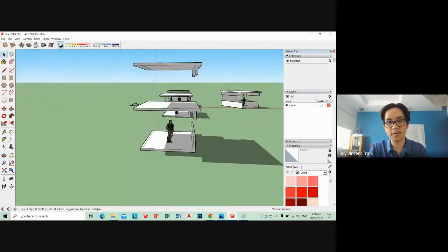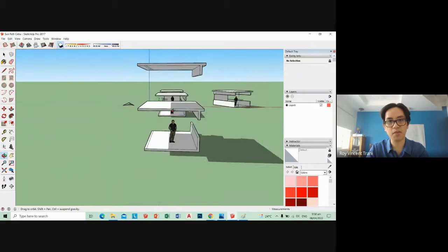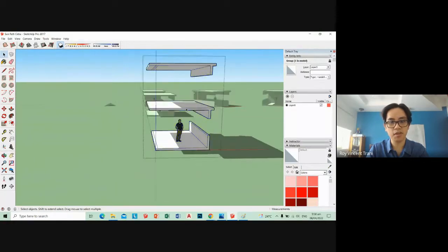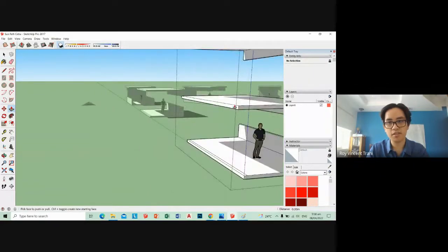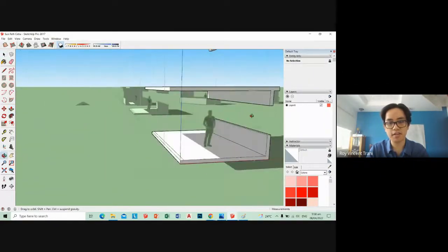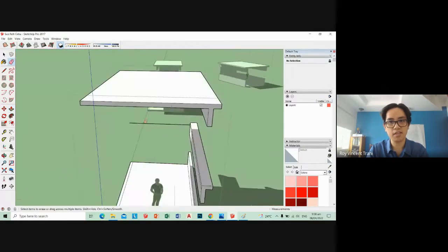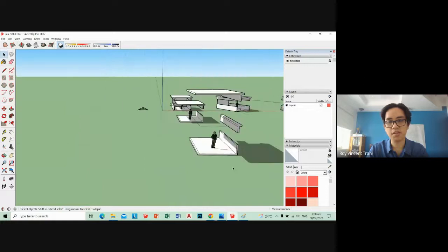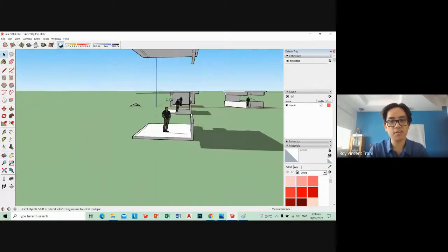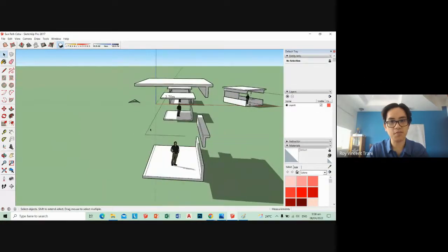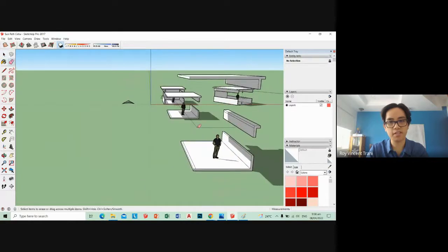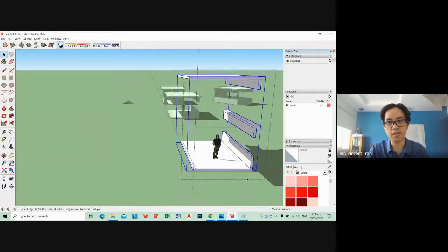Let's say you have a floor above it, not so much a problem, but what happens when you make it a high ceiling, with no floor above it? So even if you just move it like that, let's say high ceiling all throughout, with white floors at the top, your ground floor will be totally exposed to the sun. So this will mean that you might want to do your double facade system, but again, that might be a bit too bulky and too expensive.